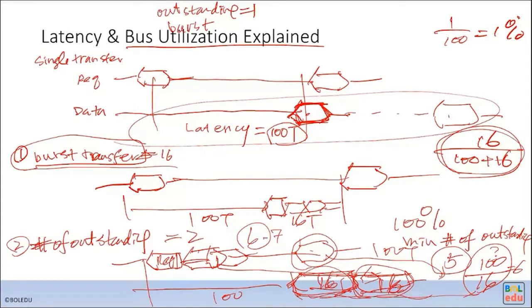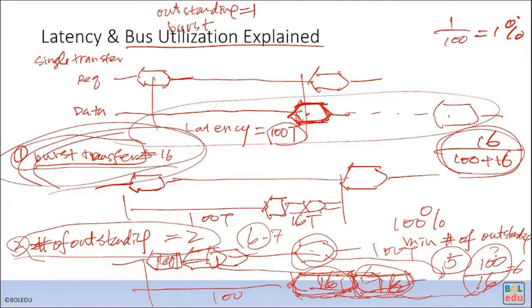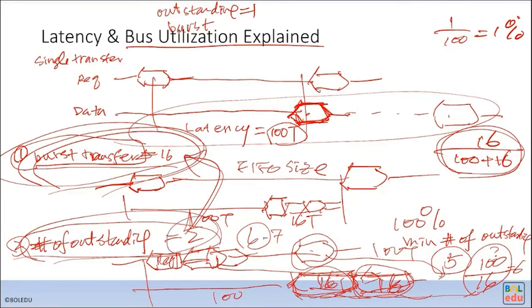Remember, you don't want to put a big number. You have to use this number wisely, because these two numbers determine the FIFO size, right? If the number is too big, it doesn't gain you anything, it simply creates a useless waste of resource. So you need to calculate.